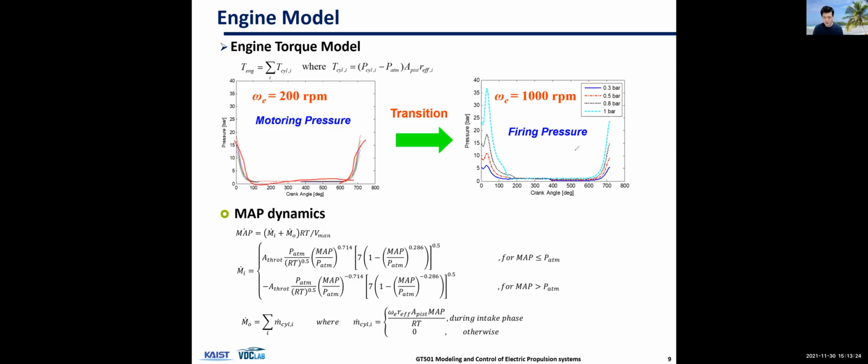But when there's firing, there's this high peak pressure, okay? So under this curve, this is what's moving the engine. This is the work the engine is providing. So this is the compression cycle, and this is the combustion and working cycle.